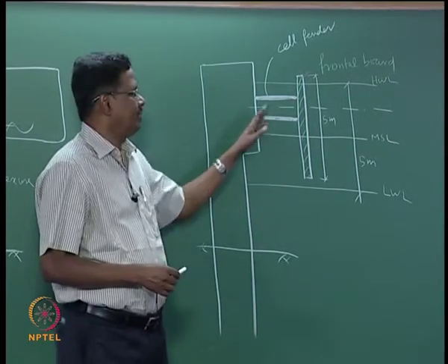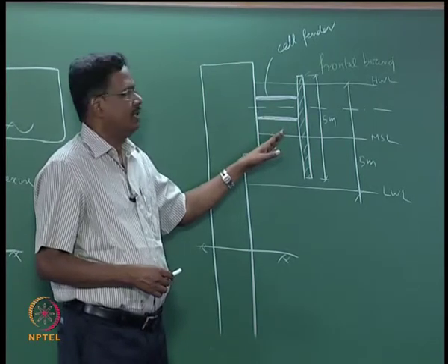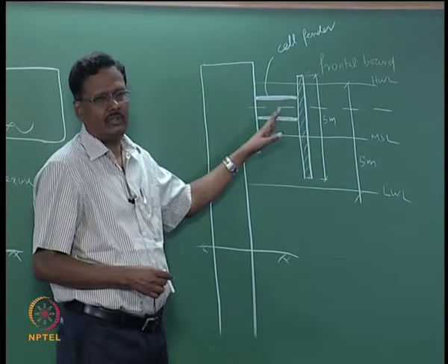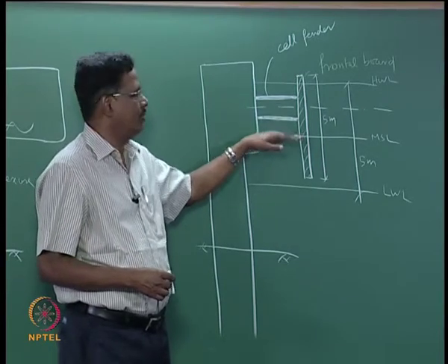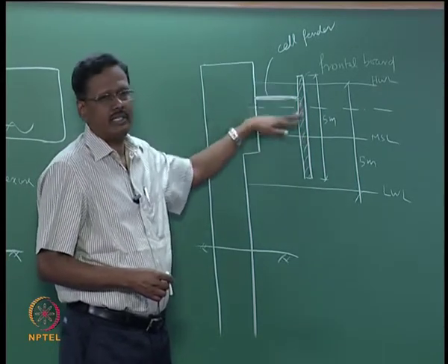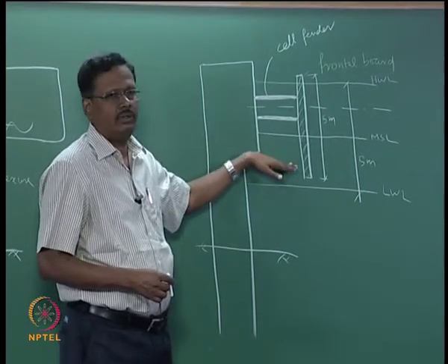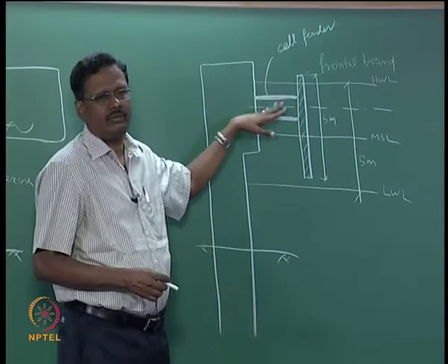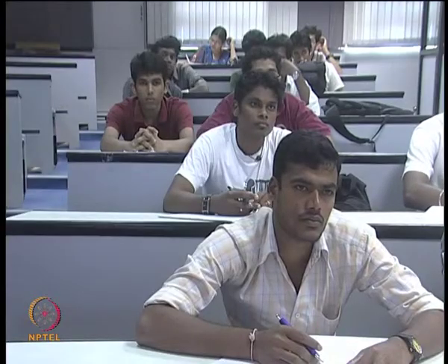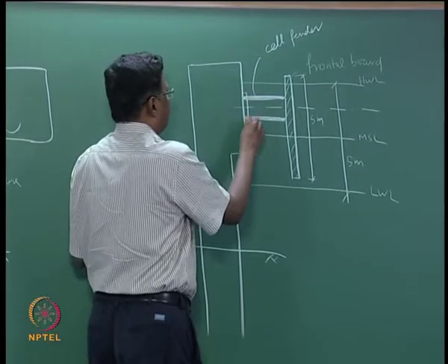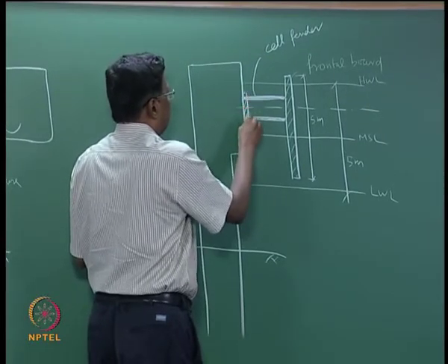See, for fixing the fender we need some time when water should not be there. So above mean sea level, at least 6 hours a day, in 2 slots it will be available. If you are fixing it below that, fixing a fender will be very difficult. That is one of the reasons why we have to fix the fender here with the concrete structure, some bolts and all.